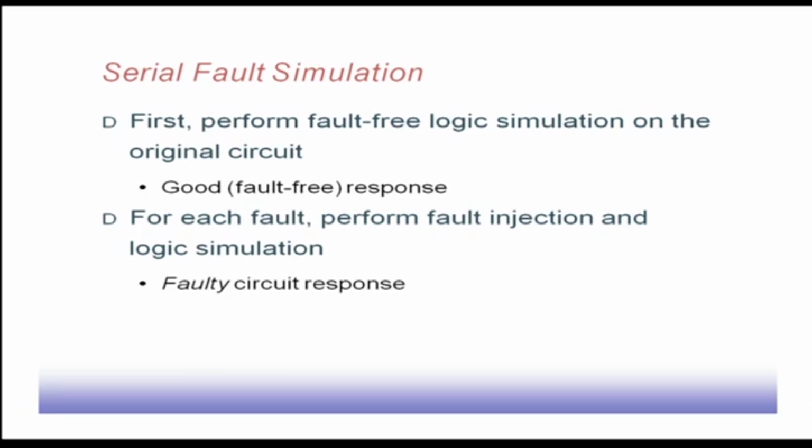The simplest fault simulation technique is serial fault simulation. So, what do we do in this case? We first perform a fault free logic simulation on the original circuit. We have got the test pattern set, and for the test pattern set we want to determine what the fault free responses from the circuit are. These are called good or fault free responses.